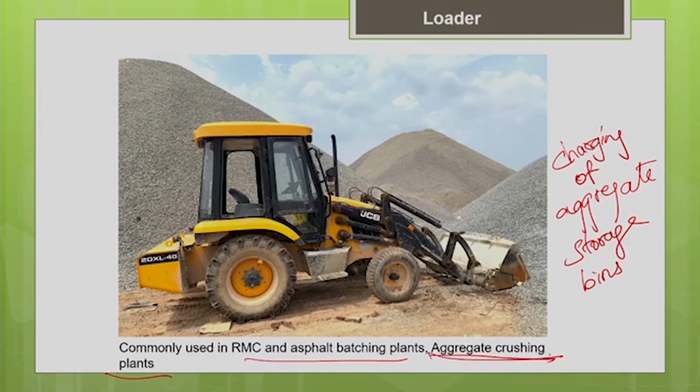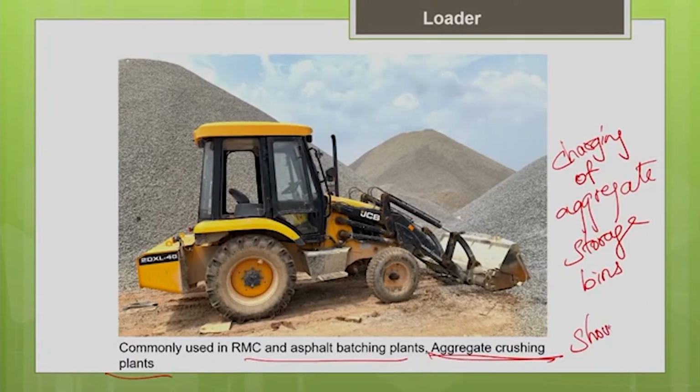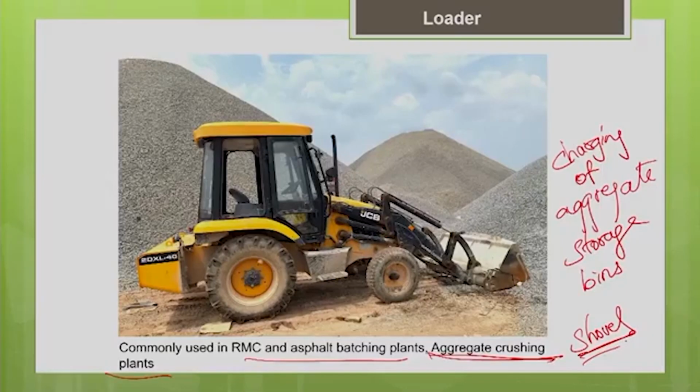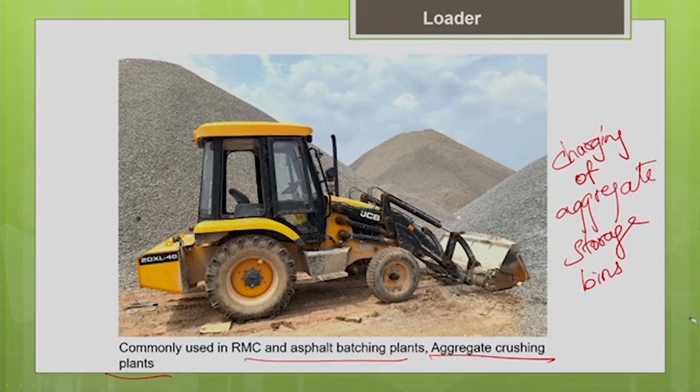See, in certain cases where the haul distance, the transporting distance, is not favorable for the shovels, your front shovel, in that case you can go for the loader, which is both good in excavation as well as it can transport it to the required distance. So, in that case your loader will become advantageous when compared to the shovel. So, these are the applications of the loader.